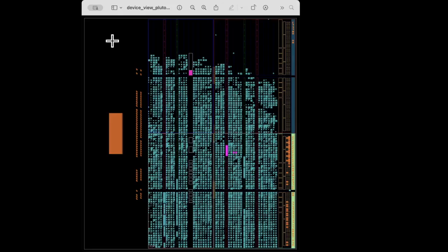That headroom is going to be taken up by randomization, forward error correction, and interleaving. And all of this will make our signal extremely resilient. Randomization makes the spectrum very efficient. Paul showed you what it looks like: lots of lobes that are nice and full, clear, random looking, taking up every bit of space in the spectrum. It's a good thing.